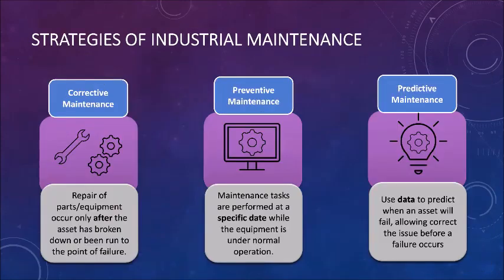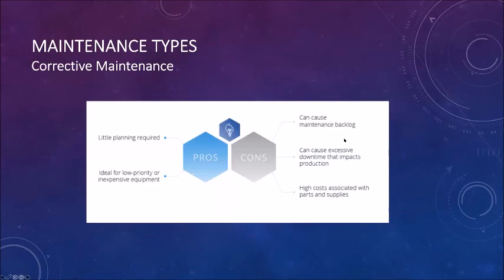In the literature, we can find different nomenclature and groupings of maintenance management strategies. Surto et al. consider the following classification for the maintenance procedure: run to failure, preventive maintenance, and predictive maintenance. The first of them, run to failure, also called corrective or reactive maintenance, is pretty simple. Fix things when they break. Since repairs are not planned, it's a good method to employ for equipment that is not essential for operation or that has a low cost. Things, any element that is rarely used or duplicates the function of other equipment.